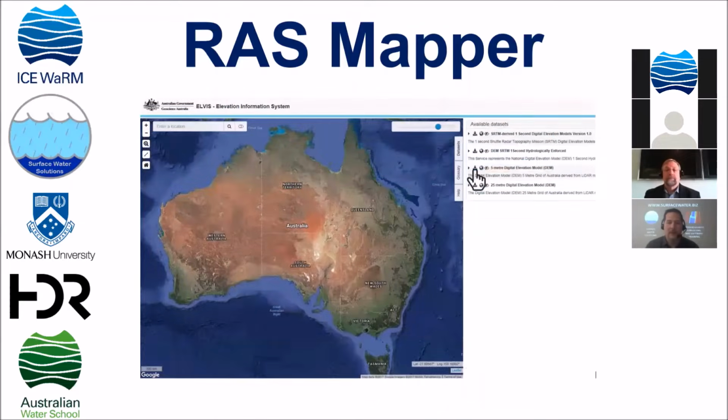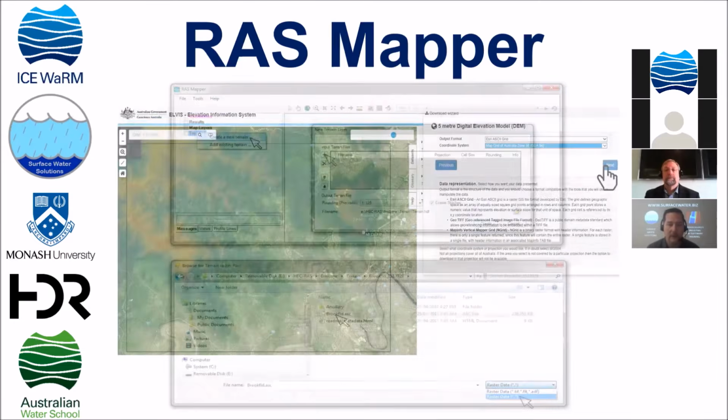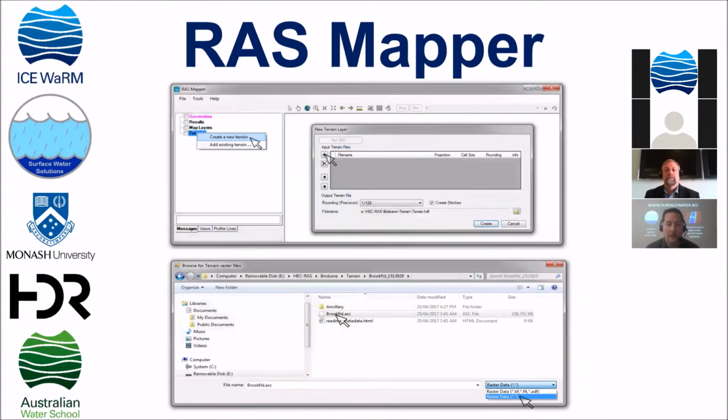Go on to the next slide. You'll see what that looks like for Australia, and there are similar interfaces elsewhere on the planet. If I go on this one and I click extract, I can go to the next slide and show you where we would go ahead and grab some data for Australia. A very relevant set of flood maps and flood modeling data in Australia is the Brisbane River. So I've just zoomed in on that one just for an example. I go and drag across my box. And once I click on that, I have to set my PRJ file and go ahead and recognize where that is. And then on the next slide, you'll see how the interface works, where you go ahead and take the downloaded file that it has just emailed to you, and you can go into RAS Mapper, create a new terrain, hit the Add button, and then you can pick any number of formats.